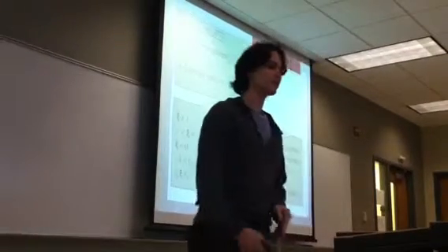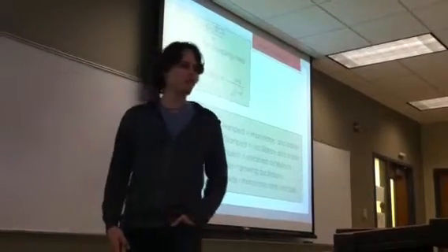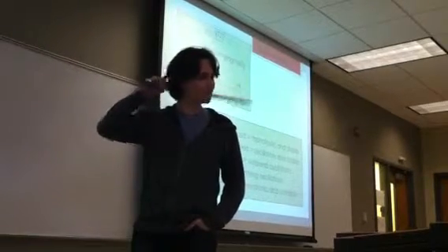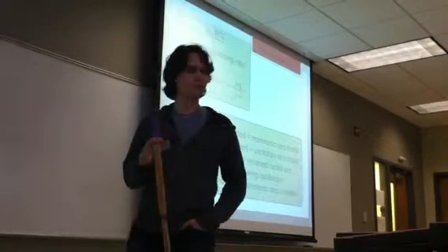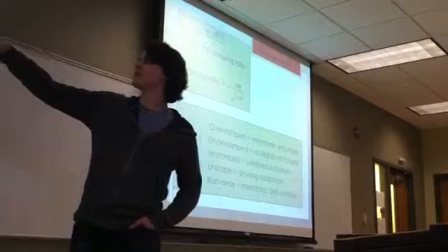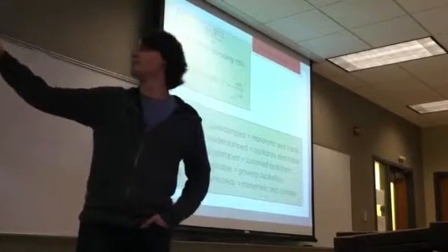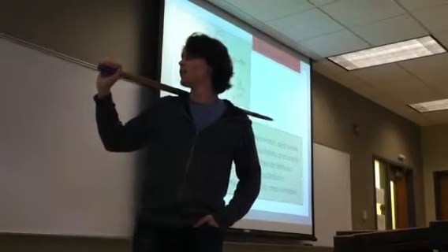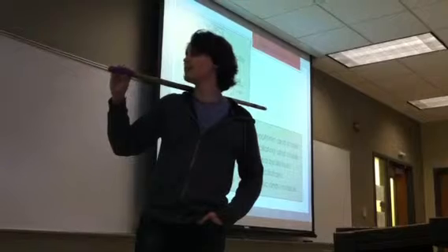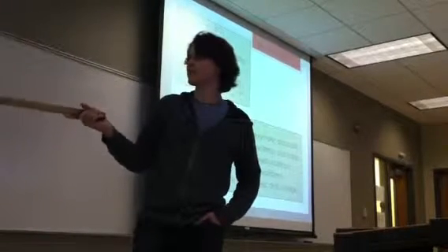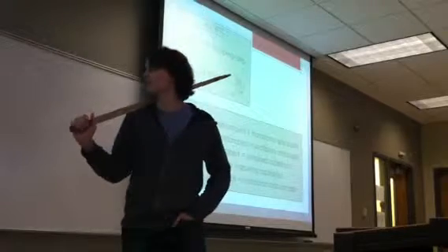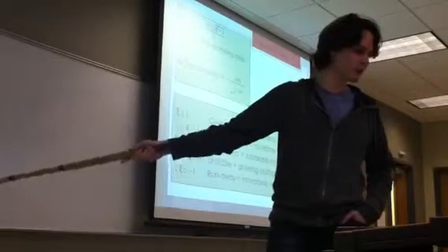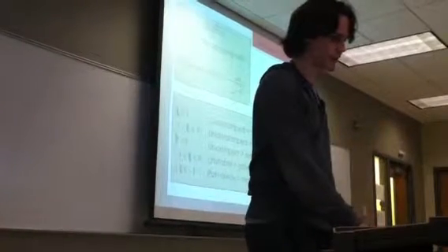Here's the root-locus theory. The roots of the first order plus dead time open loop equation are listed here. Zeta is the damping ratio. The decay ratio is listed there. We're interested in creating a stable system, so we're interested in all of these which are labeled stable and oscillatory.